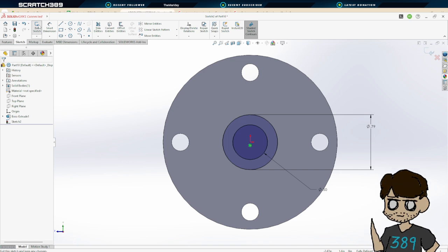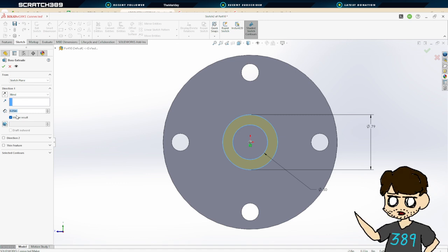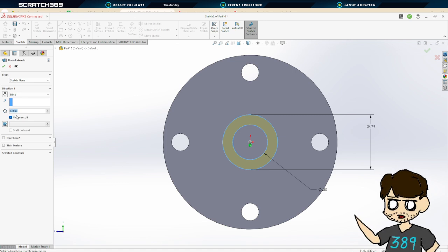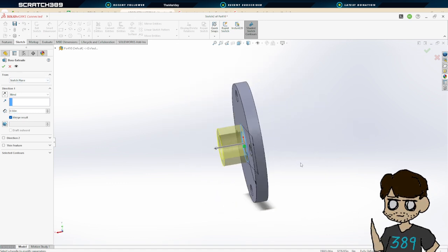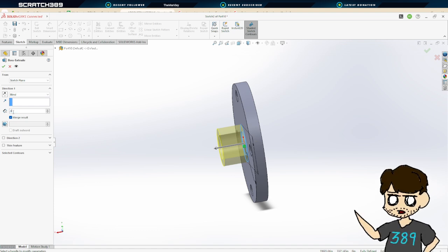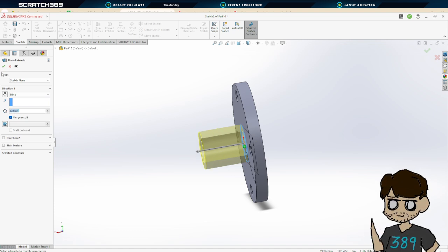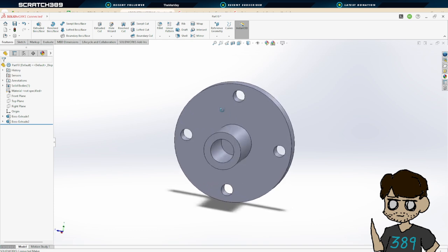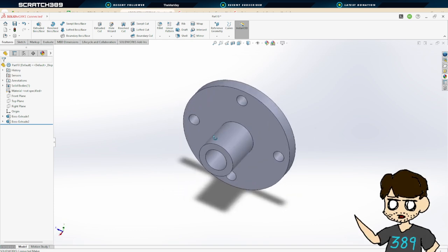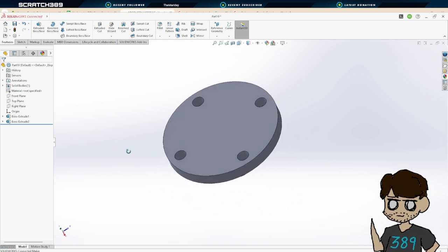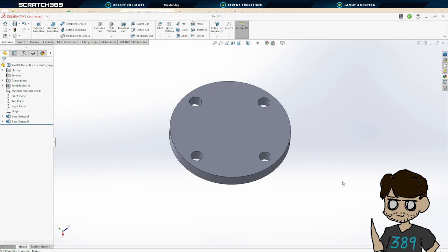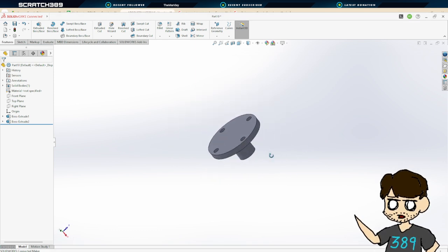Exit sketch. And I'll extrude this out to like 0.5, so that way it's just right on top of the T. Actually, no, 0.885. Yeah, that's good. So this one is also a part of the motor holder, but I guess I'll make it teal as well.